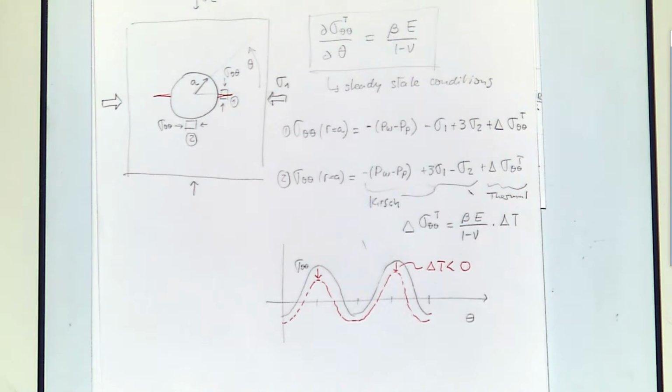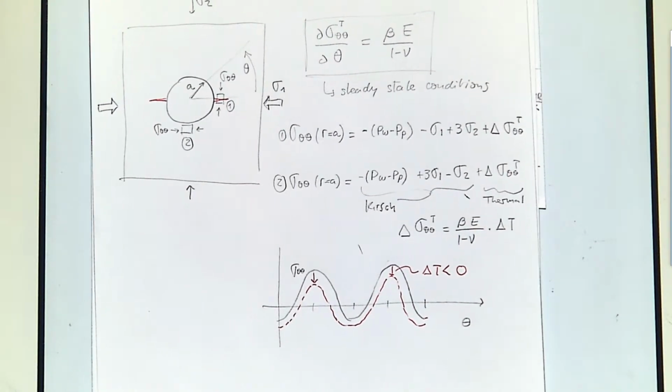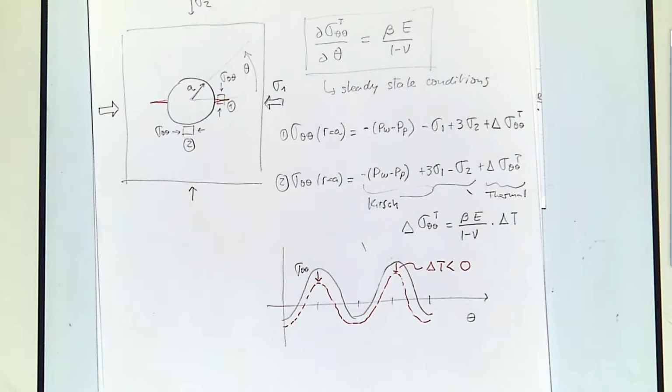And this is very important for wellbores because, as we said before, sometimes you change the wellbore mud temperature, and that may trigger changes of stresses that then produce mechanical failure in the wellbore. You may have events of low circulation just by changing the temperature of the wellbore.